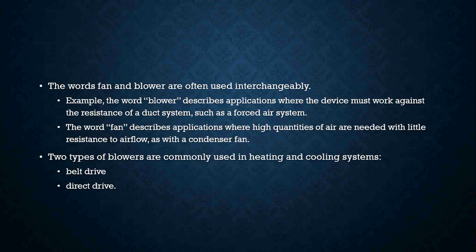When we think about the terms fan and blower, honestly, in this field they are used interchangeably. The term blower is used in applications where the device must work against the resistance of a duct system, such as a forced air system. The word fan is used in applications where high quantities of air are needed with little resistance to airflow, such as a condenser fan motor on an air conditioner.